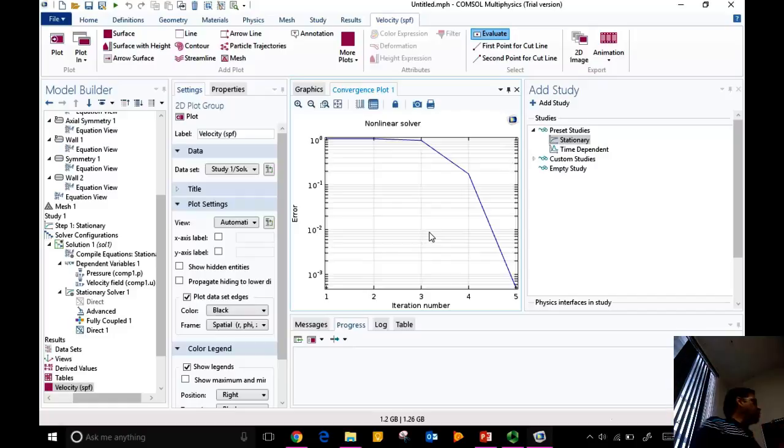That depends on the gap width, the kinematic viscosity of the fluid, and the internal rotational speed. And when that number is 1706, if it is below 1706, you should get this solution. If it is above 1706, you'll get these cells.